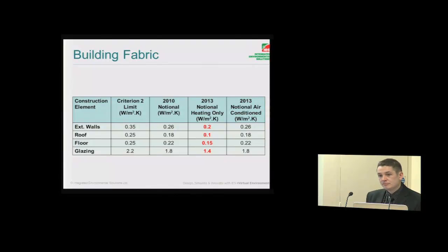Okay. How do they define air conditioned? Has it got to be fully mechanically ventilated, or can it be naturally ventilated and you just add air conditioning? I believe it's anything with cooling is their definition. People are just going to buy it. I mean, well, that's precisely my concern about it. What I can see happening, if it goes forward with the parameters in this consultation, is that the building perhaps only needs to have heating, but will have perhaps split systems put into it. So the notional building would qualify under the air-conditioned option, making it a much easier target to hit.